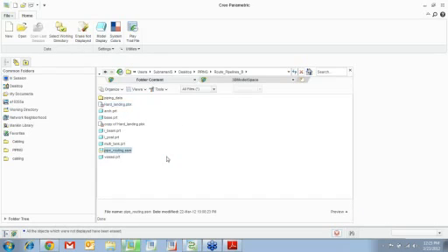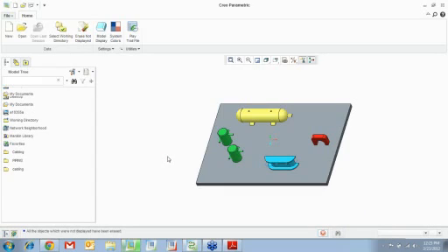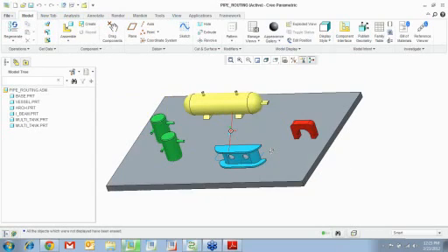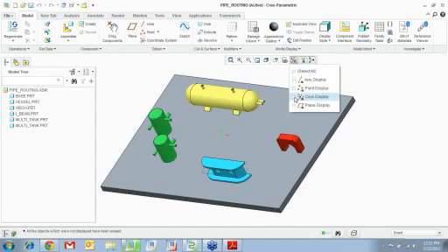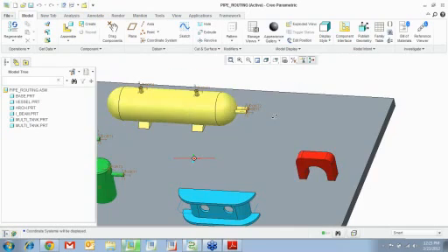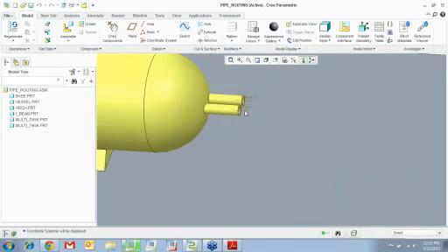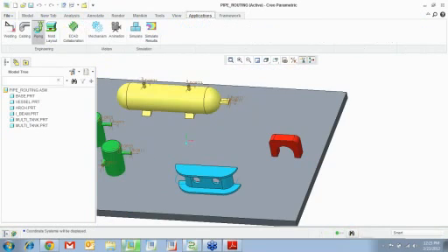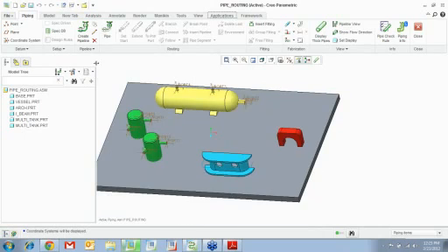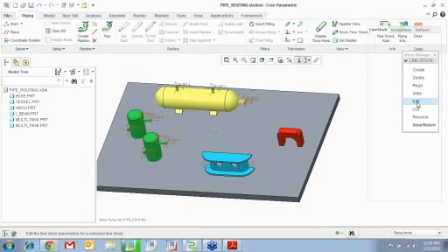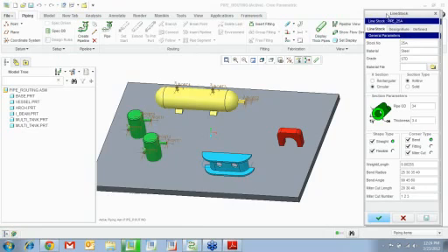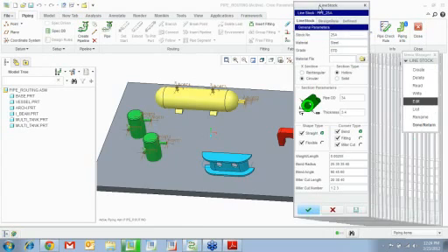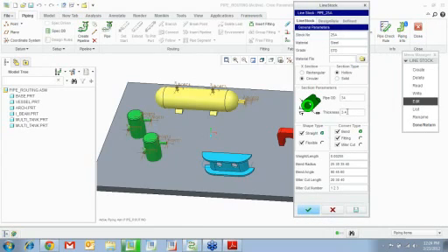So I'm going to open this pipe routing assembly. You can see, here's your pipe assembly. Want to turn on the coordinate systems. Again, you have to be careful and make sure that your Z is pointing outwards. Okay. Now, what you need in here is a line stock. So you can go to what's already there, then edit it. You can see that it is a 25A stock, pipe OD, pipe thickness.